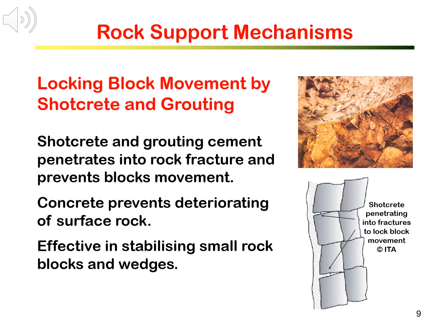As shotcrete is applied by spraying cement onto the rock surface with pressure, cement not only covers the rock face, but also penetrates into the rock mass and fills some of the joints opened at the rock surface. This effectively locks the rock blocks from potentially loosening and moving. This is illustrated by the diagram on the right. The concrete layer covering the rock surface also helps to prevent the deterioration of the surface rock.